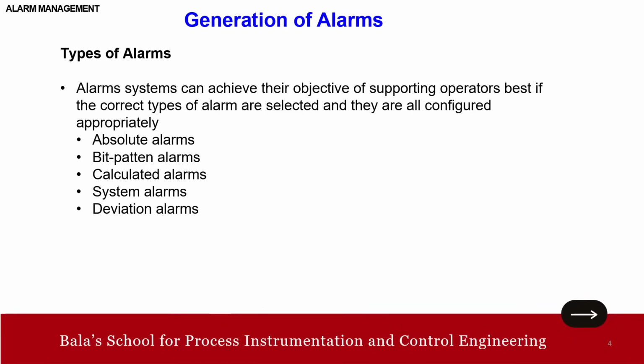So typically it is used to compare a controlled variable against the controller set point, and to warn that the control system is failing to operate effectively. Here care should be taken that the alarm is not generated during large process disturbances where the control system is doing the best it can, but the control error is large.